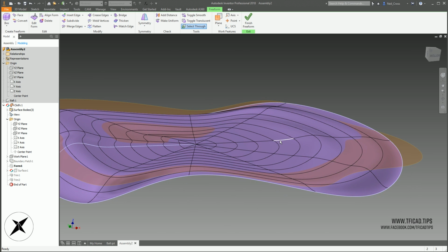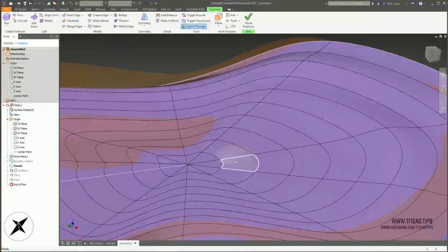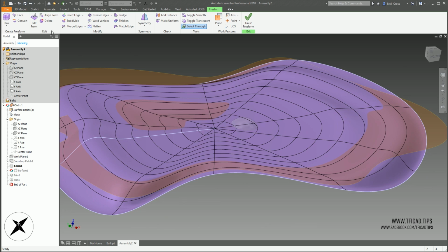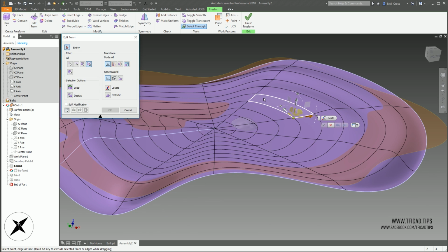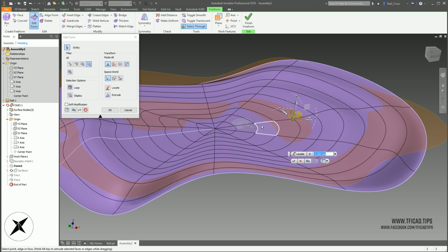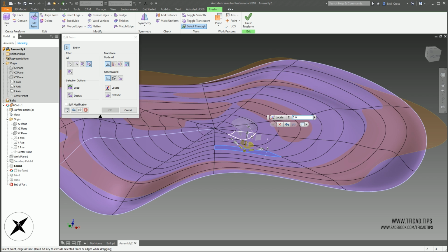Here's another thing, a good thing you can do, right? Because at the moment we can't see the ball in the background. If you right click on the assembly node here and then turn on its visibility, that's where the ball is, that's where your surface is, and that's where your cutout is. So if you are pulling the cloth around, you can choose to either avoid that spot, or if you want to actually be brave and pull it around. But like I said, if you do make things a little bit too extreme, it might fail. It depends on how it solves it as it's moving across. But we'll cross that bridge when we come to it.